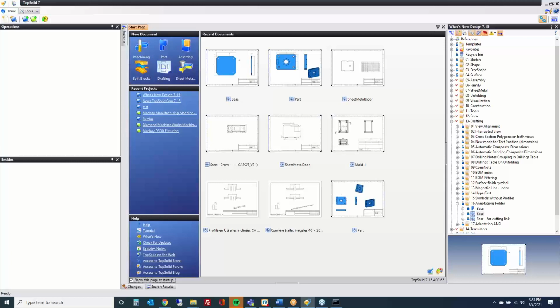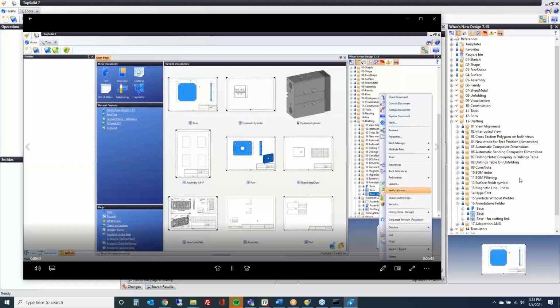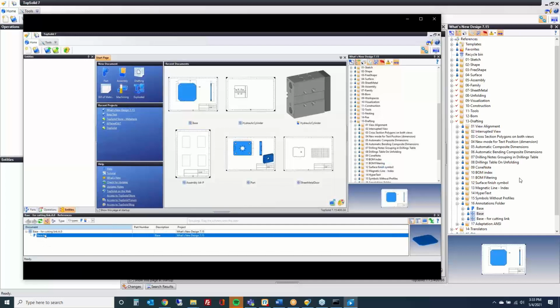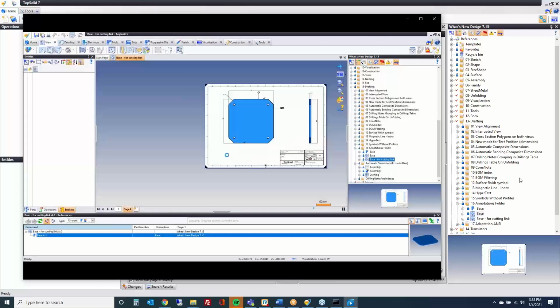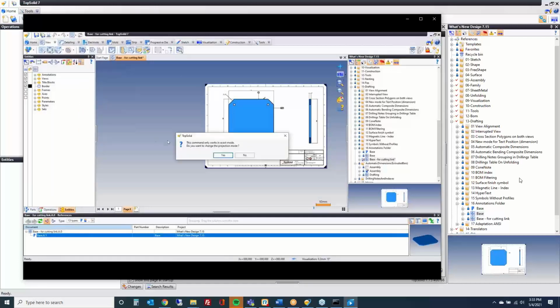All right, so let me load the next video. So it is now possible to cut the link in drafting. In other words, you're isolating the drafting. Let's take a look. So here, if we go to the pull-down menu, you can choose isolate the drafting.